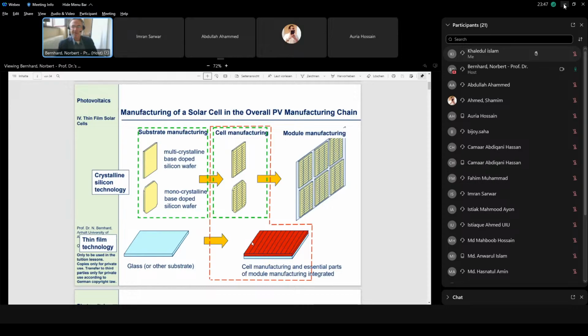In this case, it's tin oxide, and here I also added the extrinsic dopant. It's usually doped by fluorine. Fluorine is group 7 in the periodic table, oxygen is group 6, and therefore if we replace an oxygen atom by a fluorine atom, we have one surplus electron, and this makes, of course, an n-type character of this material.